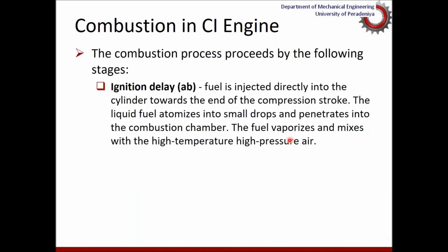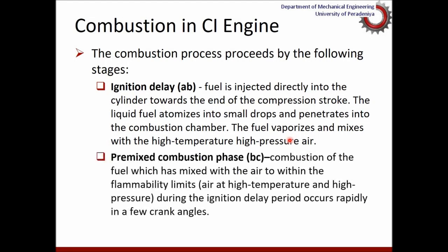So those are the stages in combustion in compression ignition. First, the ignition delay is the time taken for the atomized fuel particles to penetrate into the combustion chamber and mix with air particles. Then comes the pre-mix combustion phase, where the air and fuel already mixed during the ignition delay period start burning.